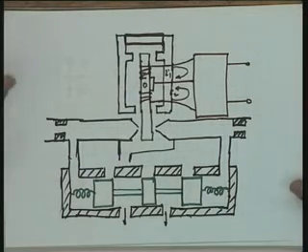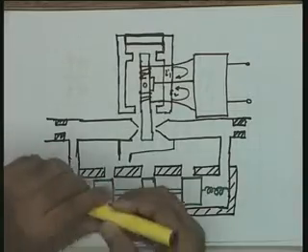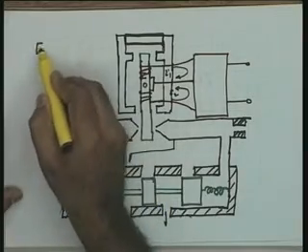So you see that when it comes to control, you want to go for either a digital computer or op-amp based circuits, and when you come to actuator, you want to opt for a hydraulic actuator. So it means really there should be a suitable interface between the two, a suitable device which connects an electronic controller to a hydraulic actuator, and this electro-hydraulic valve is going to serve that purpose.